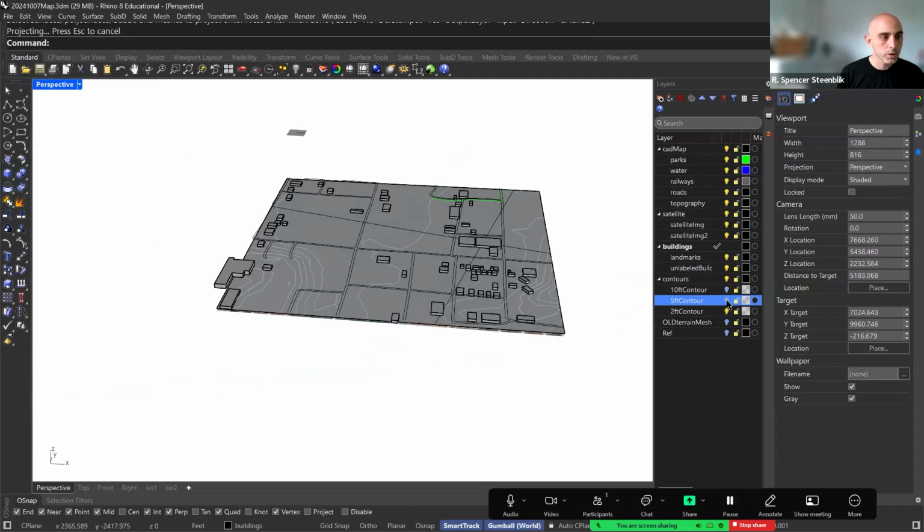Let's see about how well those interact. Yeah. So if I were going to do this again, I think I would probably do them in intervals that align, so that I don't have, you see how the 5-foot contours don't align with those 2-foot contours. I would probably do like 1.5 foot or whatever divisor you need in order to make sure that you get that. So maybe it's like 3 and 6 and 12, or yeah, 9, 12. Yeah, so that might work. Actually, 3, 6, 9, 12 contours might be a good one to go with, or 1, 3, that might work well. Okay, so we've got that kind of squared away.